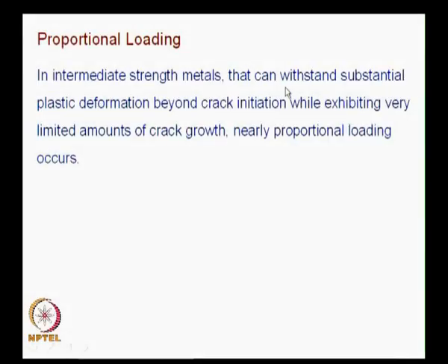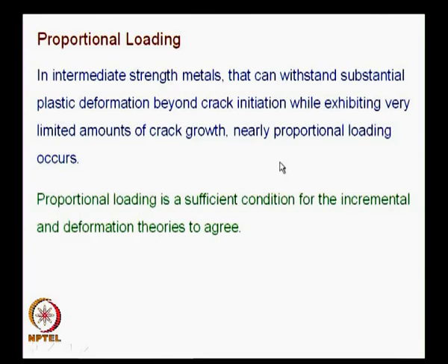So, when you have two free surfaces, the stress has to be redistributed, and what you are trying to say here is certain materials can withstand substantial plastic deformation. So, essentially there is no significant crack growth. So, nearly proportional loading is possible. That is the way we have approximation, and this is again re-emphasized. Proportional loading is a sufficient condition for the incremental and deformation theories of plasticity to agree.